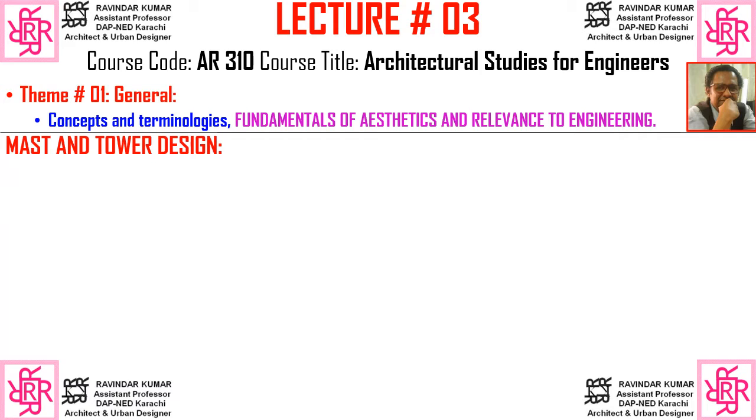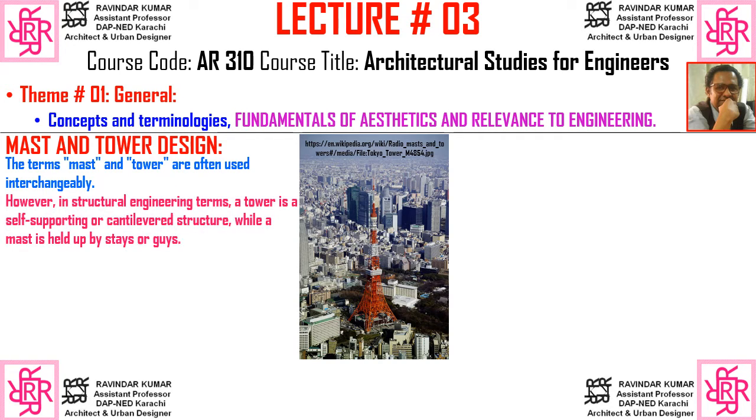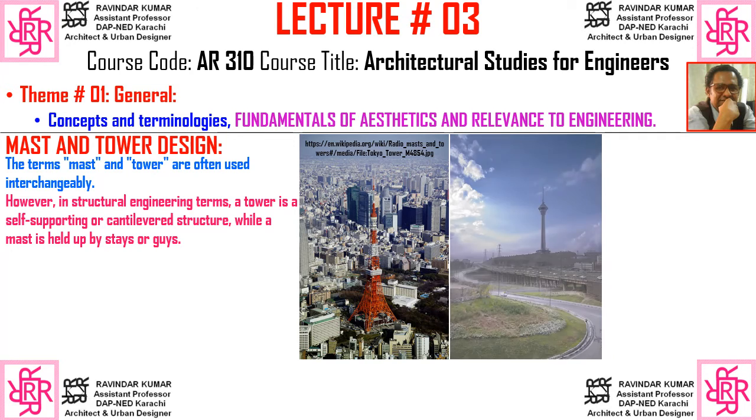Next example is mast and tower design. The terms mast and tower are often used interchangeably. You have seen this kind of towers in our city. However, in structural engineering terms, the tower is a self-supporting or cantilevered structure, while the mast is held by stays or guys.